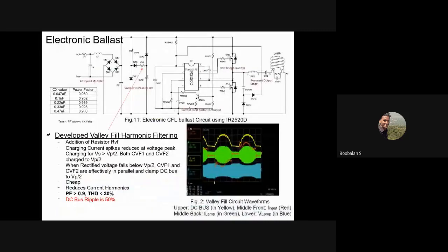Anyway, this is a real-time thing, captured from the scope of a power analyzer. My voltage looks like this, my DC voltage looks like this. Somewhat it's not a pure DC, and the current is not pure either. So there is a huge error, a lot of up and down spikes, as we will see. This is due to my switching devices, maybe MOSFET or IGBT, their switching transition time, so my input voltage is also getting affected. We are giving input voltage over here, and this also gets affected.